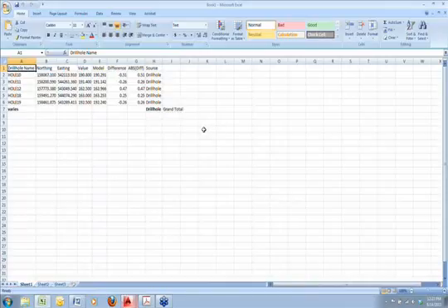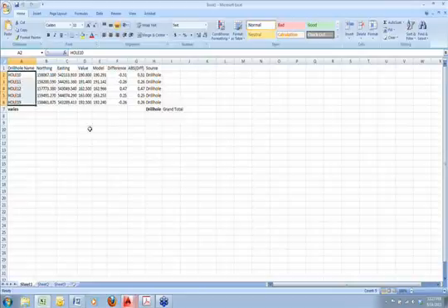So of those 12 holes, it looks like 5 of those are over the 0.25 tolerance that I entered in. And it tells you the drill hole name, the coordinates, X, Y, and Z. And it tells you what the model, the surface has, and then also the drill hole itself. So it just gives you a check to see how close they all are, and lets you decide if you need to go and remodel.